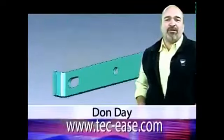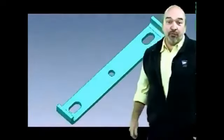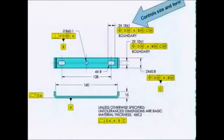Controlling slots and other irregular shapes has always been a challenge. The standard gives us two ways to tolerance slots. The first works for slots only. The length and width of the slot are toleranced as two features of size. A position tolerance with the word boundary is applied to each position tolerance.